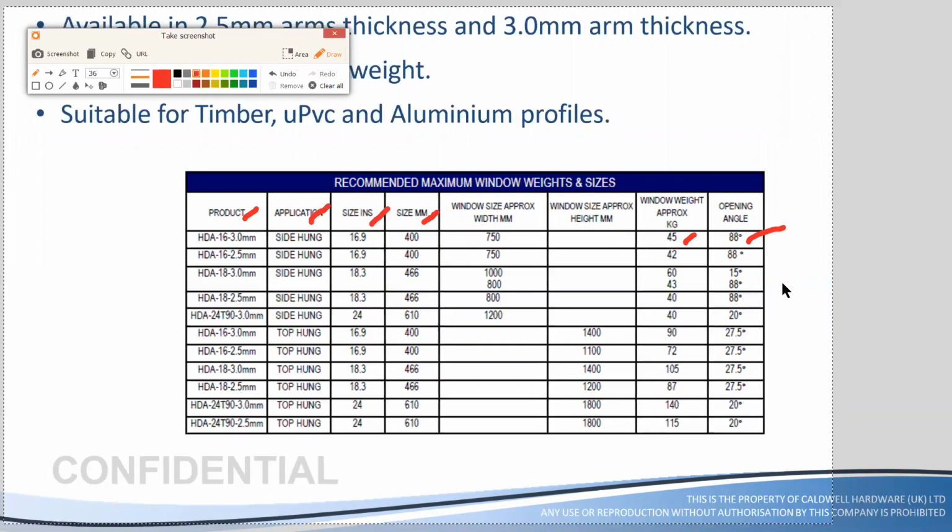But you will see normally, apart from one hinge, all the hinges or almost all the hinges are locked at 88 degrees. The reason for locking the hinge at 88 degrees is this: if this is my window inside, and you open it completely to 90 degrees, the window and the slider get locked and jammed at that particular angle, and unless you provide a jerk there, the slider doesn't get released and come back.